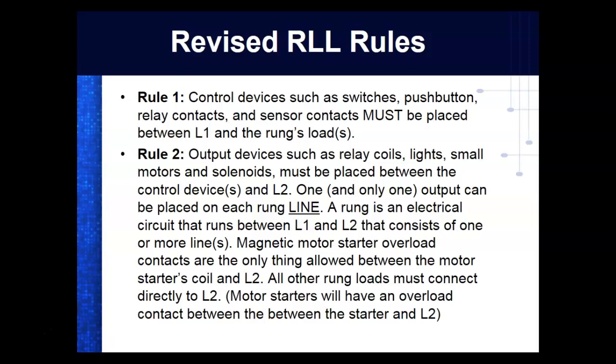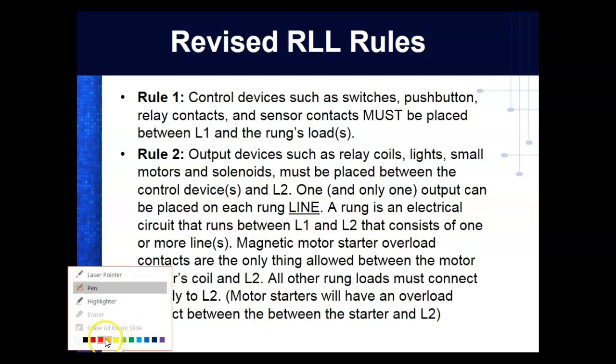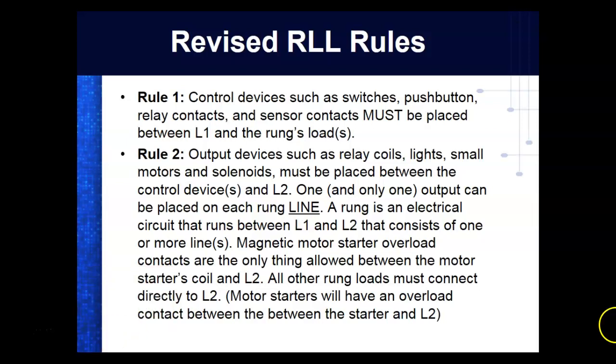So what we do is we have a sensor inside the motor control, inside the circuit. So this is three phase. These would be the contacts to run the motor. And then over here, these are symbols for overload sensors. What these are looking for is overcurrent over a certain amount of time. And then my motor would be right here. So these are overload sensors, and we can see these on the line.